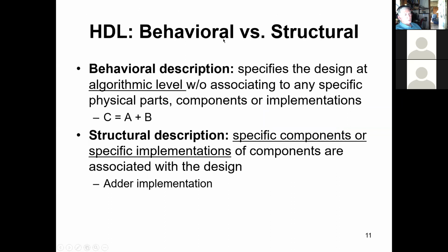We talked about this in logic design, that there are levels of description. And so when we write our HDL code, we can describe it at the behavior level, and then eventually we can get down into the structural level. Sometimes we'll talk about behavioral, data flow, and structural, and then the physical realization of it. So when we talk about behavioral description, we're talking about the algorithm we're employing and how it's going to solve the problem we want to solve, how it's going to do what we want to do.